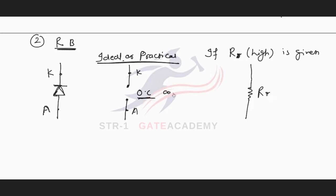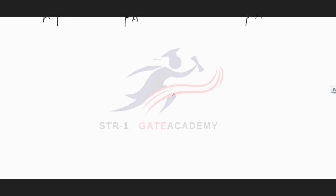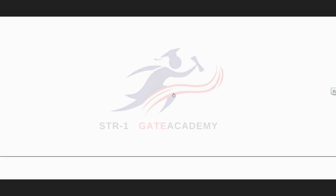It means the diode behaves like a very high resistance in reverse bias, and ideally it is replaced with an open circuit, not allowing any current to flow. These are the equivalent circuits of the diode. When we use the diode in practical circuits, it will be replaced with these equivalent circuits. We will see some examples.